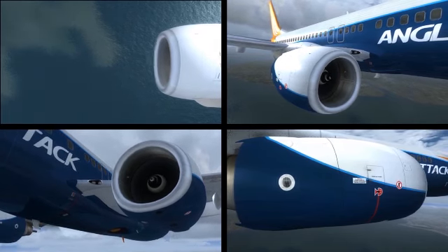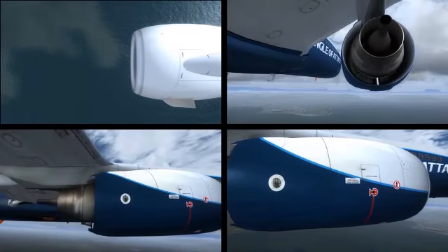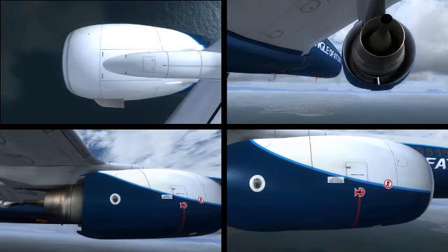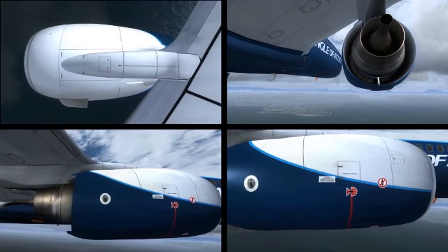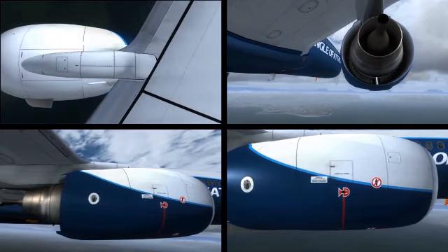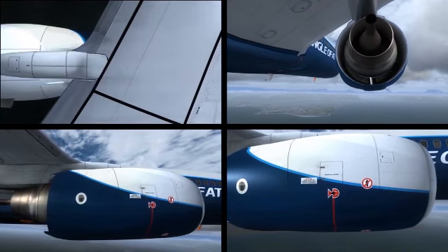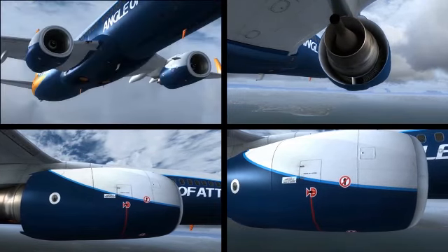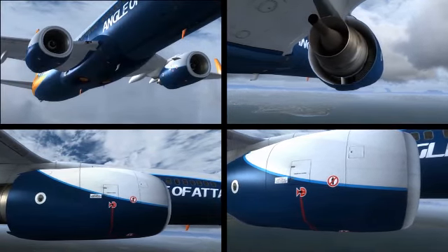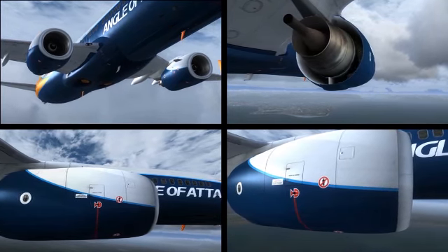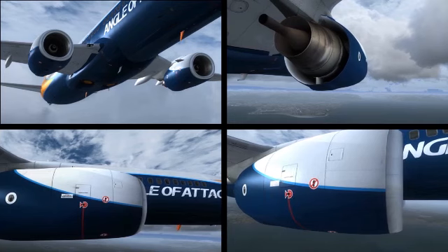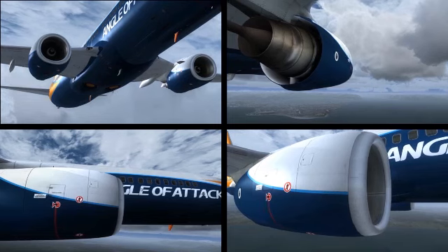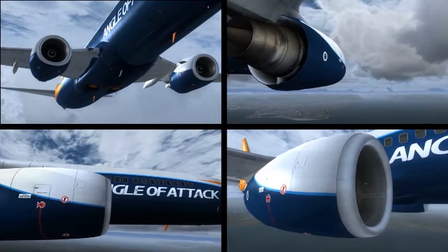The electrical system has 2 AC transfer buses, which in flight usually receive power from the integrated drive generators on the engines. Engine number 1 powers AC transfer bus 1, and engine number 2 powers AC transfer bus 2. Engine 1 also drives the system A engine-driven pump, and engine 2 drives the system B engine-driven pump. AC transfer bus 1 powers the system B electric pump, and AC transfer bus 2 powers the system A electric pump. This crossing of the power sources to the 2 main hydraulic systems ensures that hydraulic pressure will be maintained with the loss of either engine or either AC transfer bus.